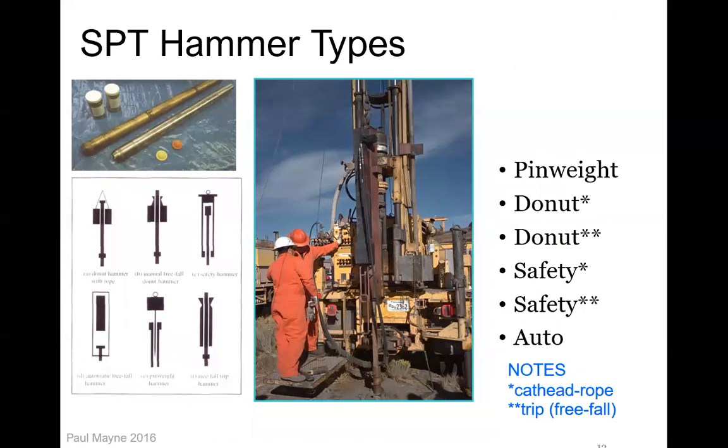Why do they take the sample out of the sampler and put it in jars before it gets filled up? Why wouldn't they just bring you the whole thing? Just transportation. It'd be difficult because these drillers are usually in remote areas, so they'll stack up these boxes, and whenever the project is done, they'll come and drop off 20 boxes. So it's all just ease of transportation. Those jars are also watertight, unlike the bags that we used in lab. They're meant to take a quick sample, get it out of the environment, and put it into a moisture controlled area.